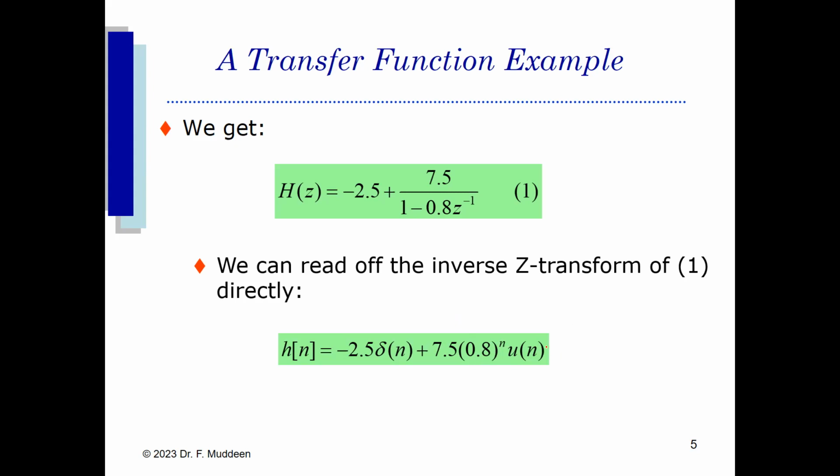And because H(z) is causal, the proper way is to multiply that by u[n]. This ensures that h[n] will in fact be a causal response. Everybody following so far? At least the technique, if you have forgotten how to do the mechanics of it?